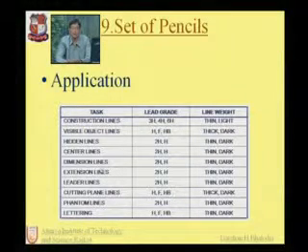Next is the dimension lines. It consists of 2H and H, which is thin and dark. Next is the extension lines. If you want to draw any line which extends in one direction or the other, for that purpose also 2H and H grades are used, which is also thin and dark.